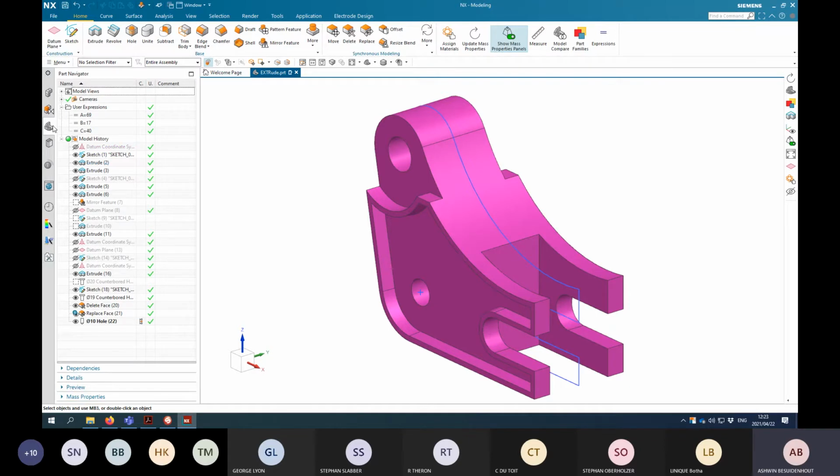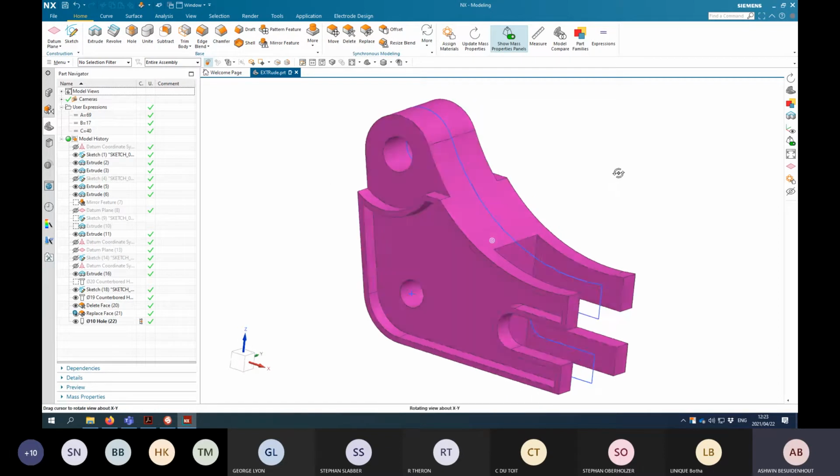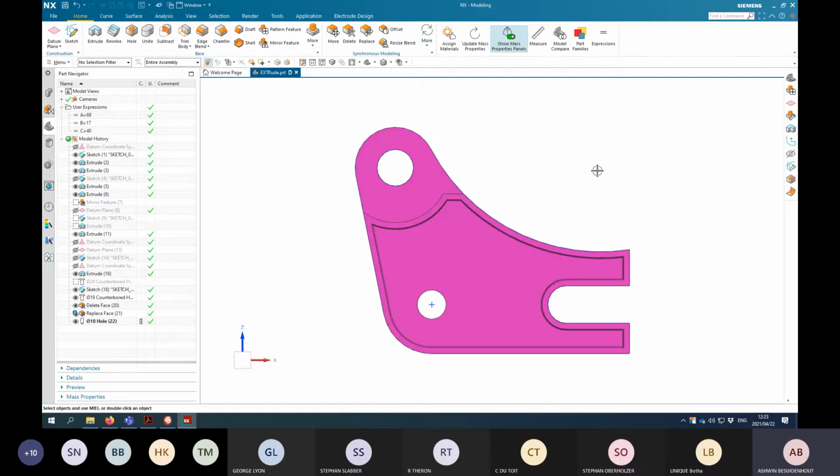In SolidWorks, for instance, you would update the existing views, put a view normal to something, and say that this must be your next top view, and then it will orientate it for you in that way.